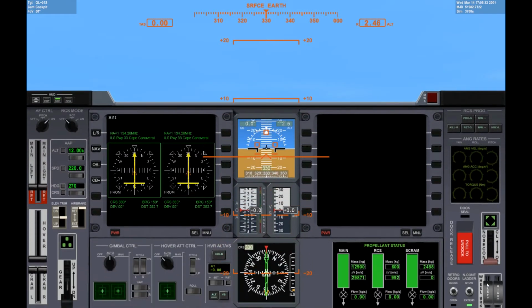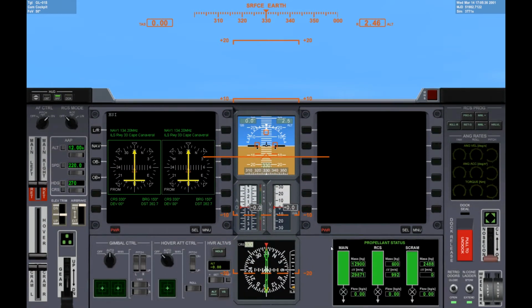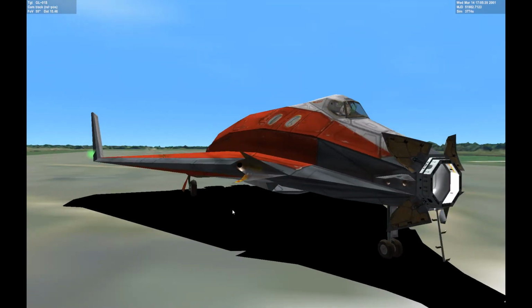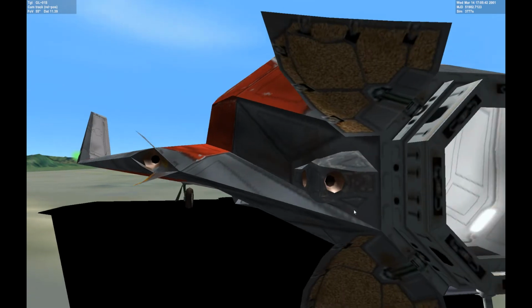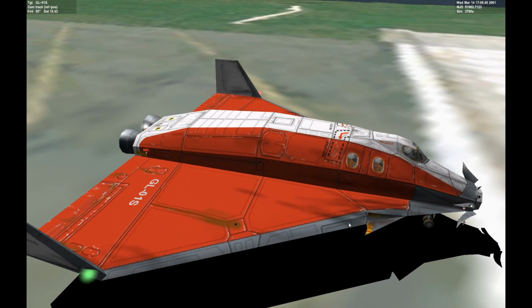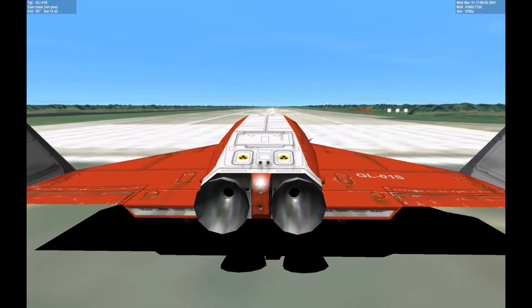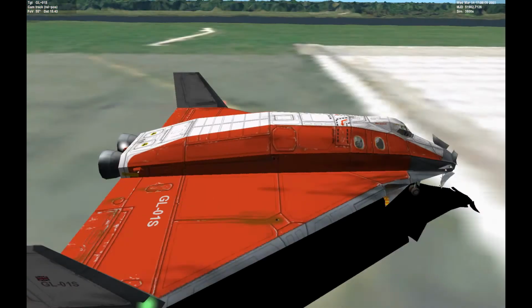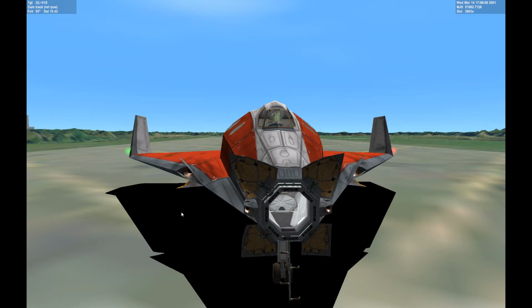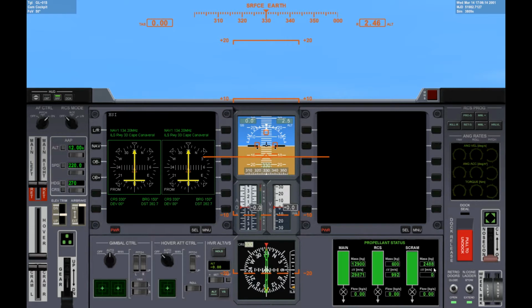The last thing I'm going to do is open the retro doors. And the retro doors will allow retro fires. These are bigger rockets than our translational ones. You can use these to slow down. Especially when you're getting close to the space station, you can use this. But not too close. That's when you use these generally. Generally what you do is you face the opposite direction of your direction of motion. Then you hit these until you get lower. Then you face the space station. And then you hit these, and then you come in the rest of the way with these. That's generally how it's done.